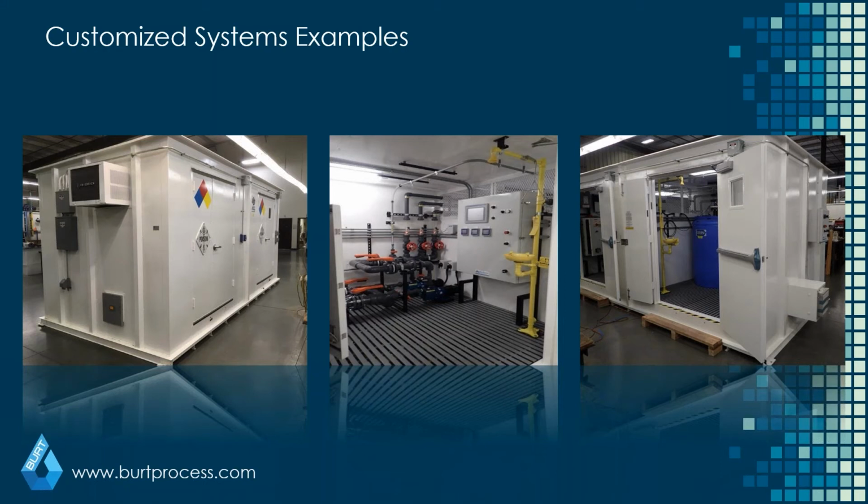Chemical safety showers can be built in, and that is true quite a bit with containerized systems. Very often they will have auxiliary equipment such as fire suppression or chemical safety showers, or maybe some specialized venting, depending upon what their actual application is. This one here also has a bottom drainage area in case there's any spills, so that you actually have some level of leak protection in your system.